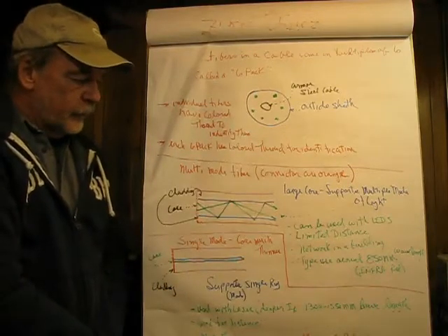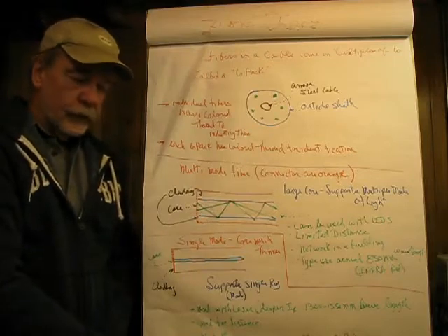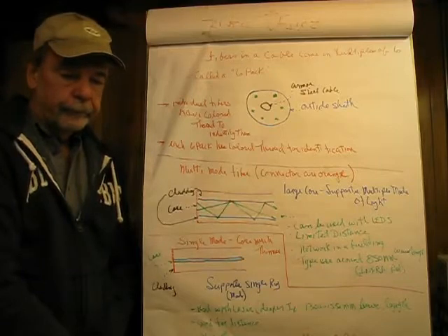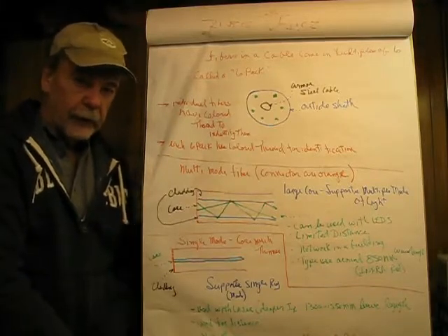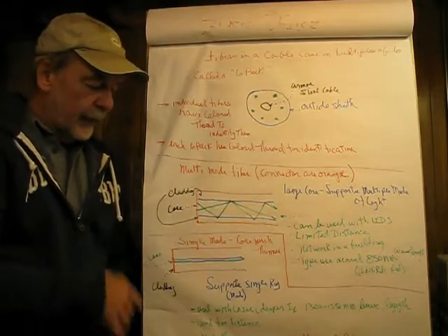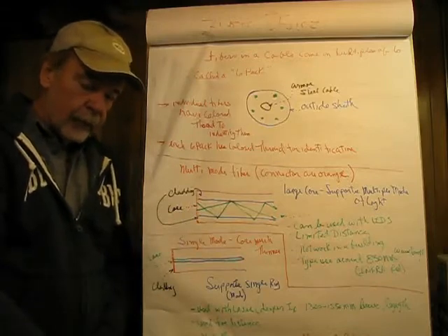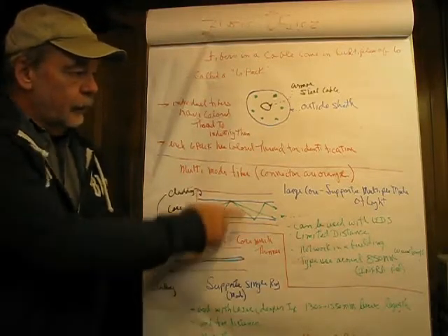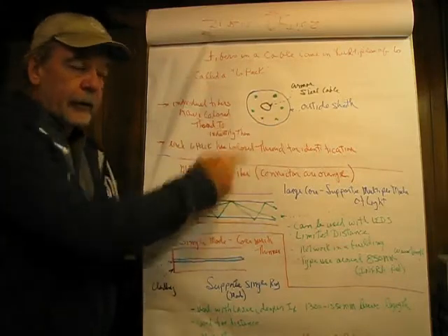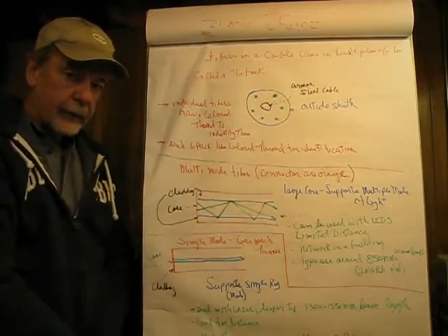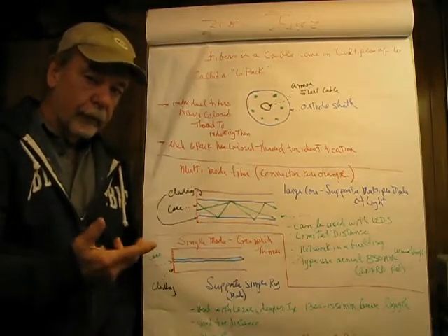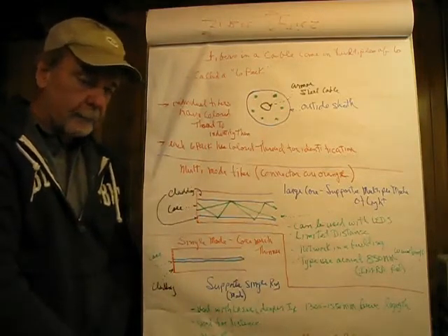So imagine that you're out on a construction crew and there's been a dig up or a steam pipe break in the street. They typically leave extra in manholes. So you go to the nearest manhole, pull out enough of this, and then you'd be using the identification to splice these so that the same fiber that was broken gets connected to the right fiber for continuity.